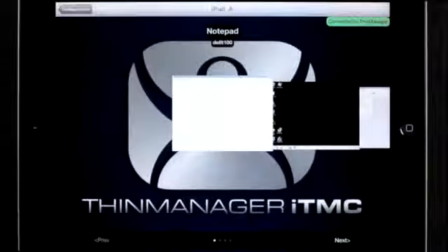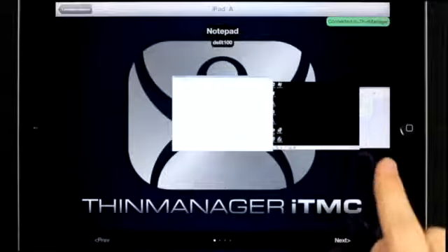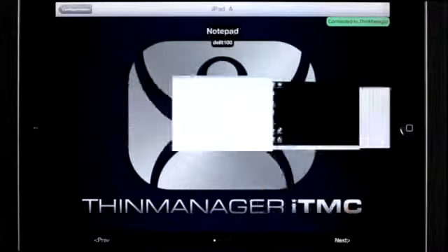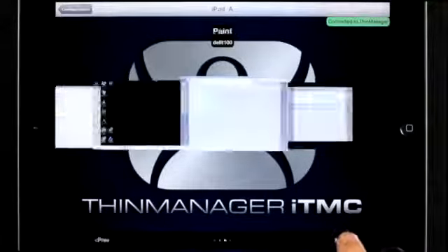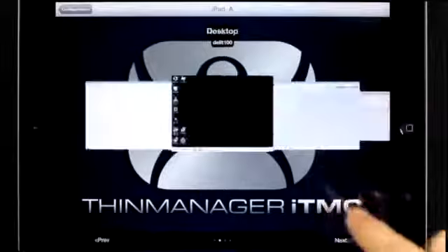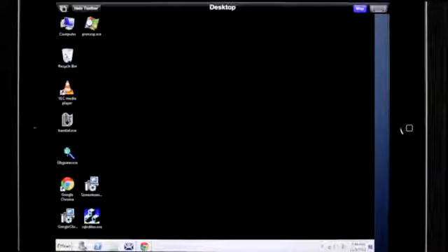Once the terminal has downloaded its configuration from ThinManager, you'll notice it'll have 4 display clients in the home screen. You can navigate through these display clients by doing a single finger swipe or by using the bottom bar at the bottom of the application. To use a particular display client, simply tap the one you want to use and it'll become full screen.